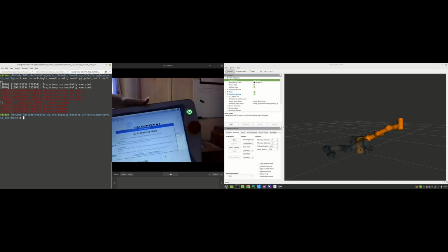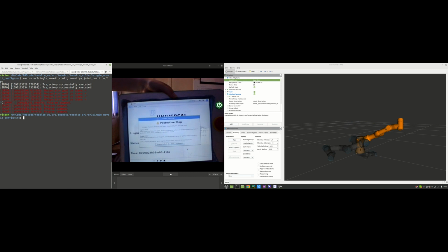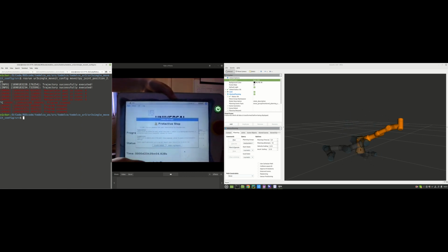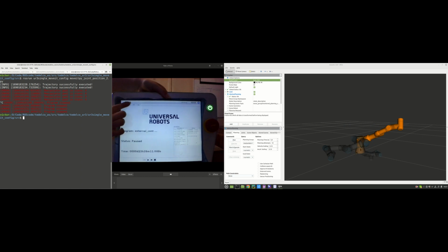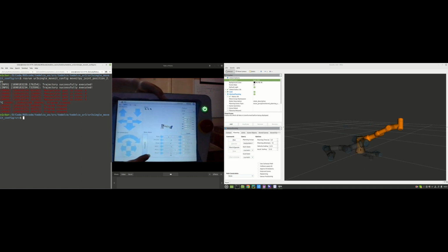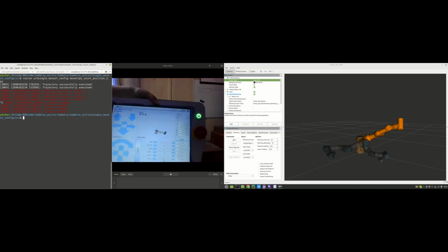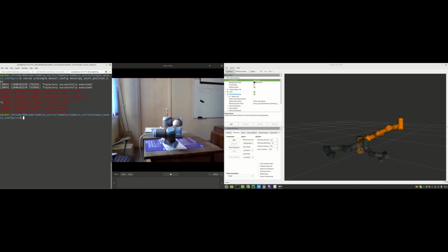What is important is that the robot automatically stopped itself when it collided with the table due to its emergency protocol. The protective stop was activated, and now we can enable the robot again, and the safe option is to set the joints to lead the robot in a safe position. We can do this from its interface or from the computer, but for now I will just modify the shoulder joint value using the provided interface.